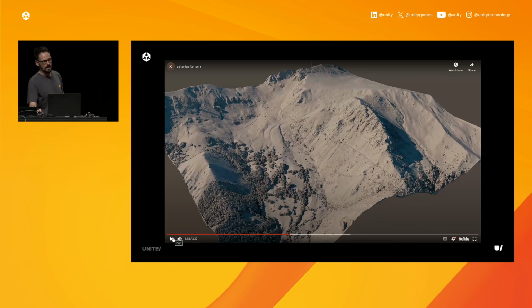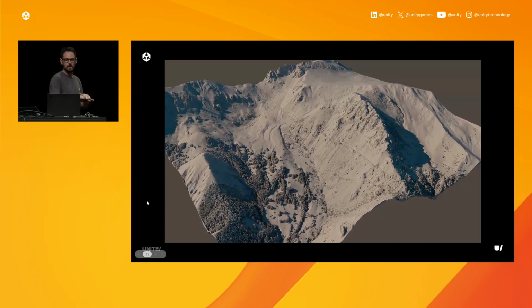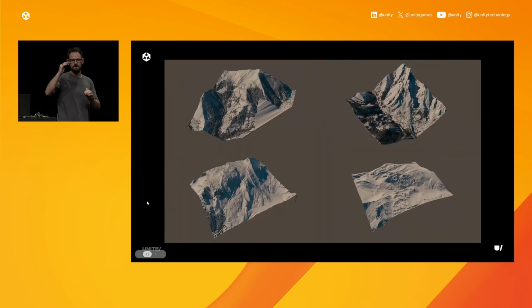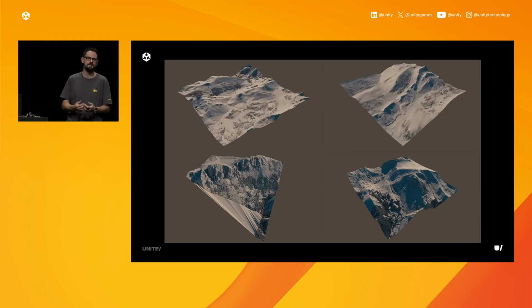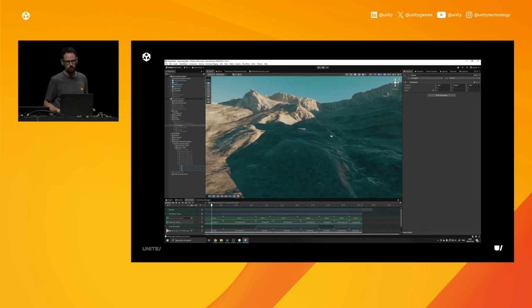So in our case, what worked very well was to flatten those point clouds, store the information of altitude for each of the points, and reproject it into voxels, right? So everything you see here, they are boxes, they are volumes, they are much easier to manipulate, much faster. We can clean them up, we can modify them, we can do anything we want.